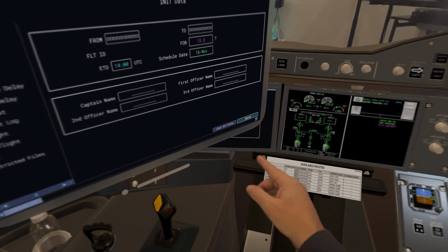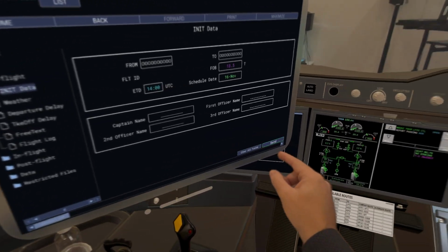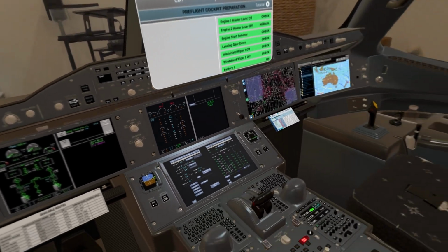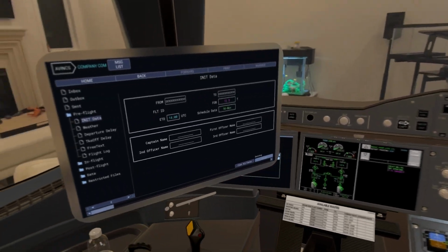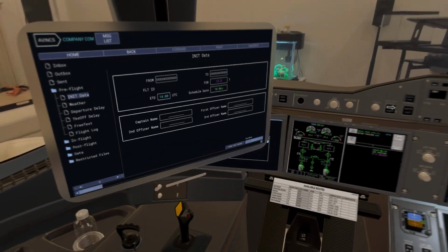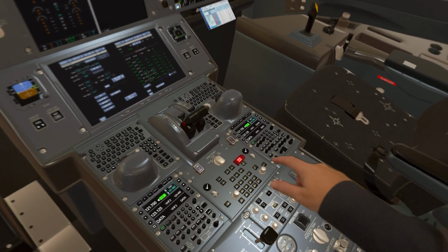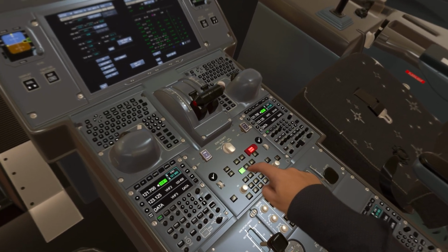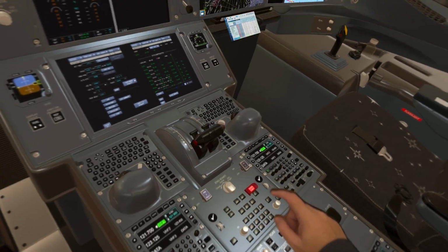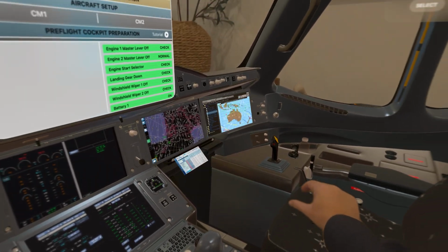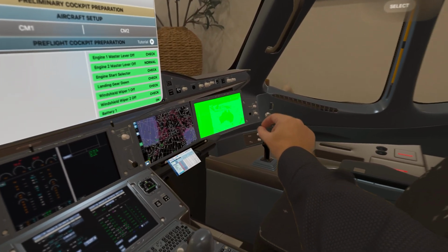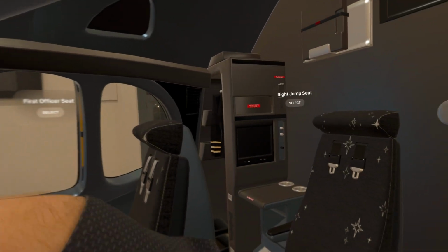Launch. ENV database and terminal charts. Check validity. OEB. Check. ECAM recall messages. Check. Dispatch messages. Check. Logbook cabin. Check. Aircraft acceptance. Perform.